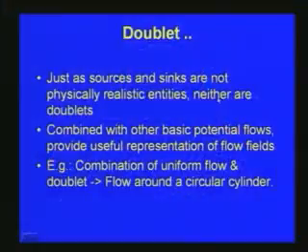Finally, just as a source or sink are not physically realistic entities, the doublets are also not physically realistic entities. We are just assuming these kinds of entities so that we can define many other complex flows. Combined with other basic potential flows, they provide a useful representation of the flow field. After this we will be discussing the combination of these basic flows, and then we will see how this doublet is useful for further representation of complex flows.